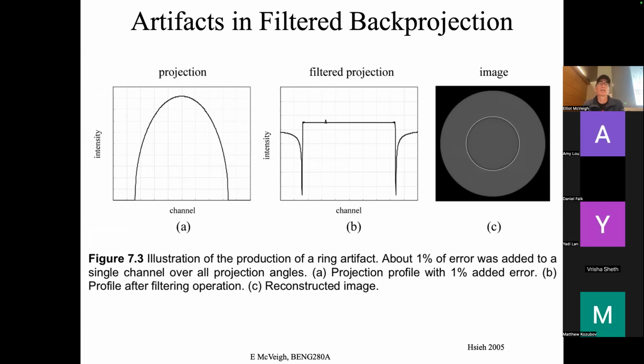These rings appear when you take images on a clinical scanner and you lower and lower the dose. When you go towards the center, you can start seeing just faint rings, because they're super hard to get rid of. The pre-calibration of those preamps, even though you did it this morning, might have faded by 5 o'clock.